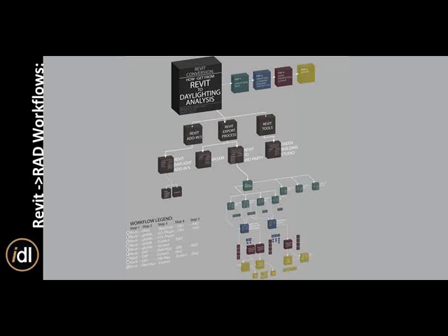The other types of metrics that you would get are visualizations: scientifically accurate perspective renderings of what the light looks like coming in, and that's where the surface reflectances play a factor. And then the last type is glare analysis. You can get luminance renderings where you can actually do glare ratios to start to understand visual comfort. Those would be three of the outputs. And all of these tools can do that to some extent, but they're all different. It's a good question.